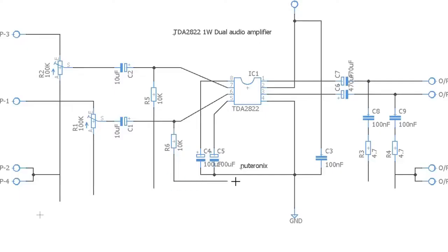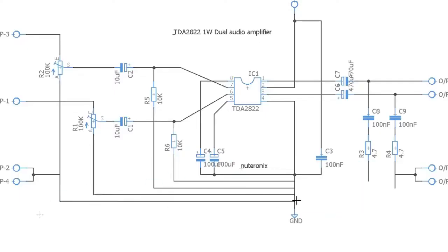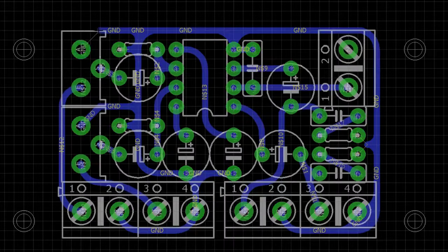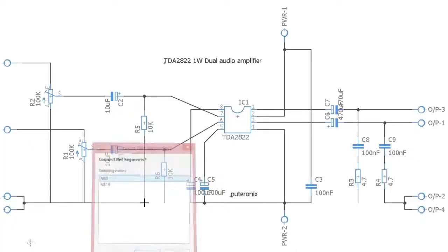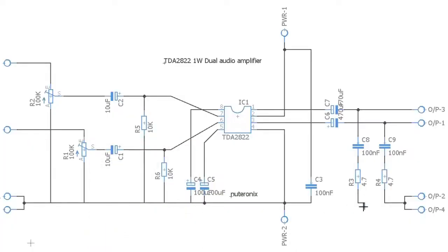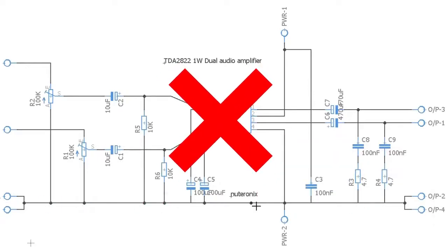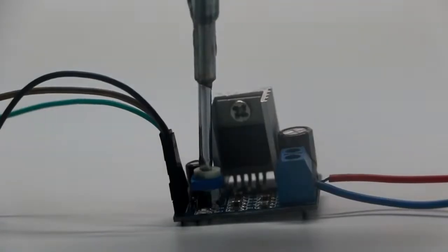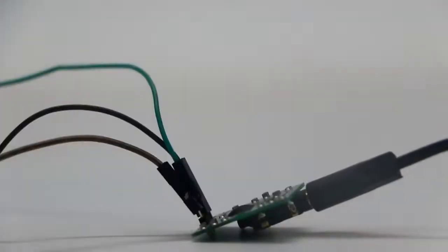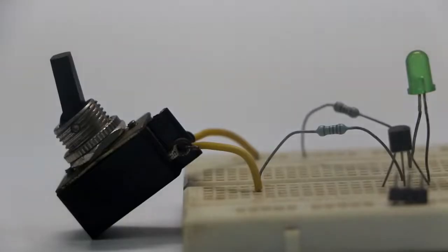When you design a PCB or wire a circuit, provide individual traces when connecting different signal references back to the ground or common node. Avoid interconnecting references together and then connecting them to the common node. Doing so will result in a humming sound or noise in analog amplifiers. This also applies to wiring of input or output jacks, tone and volume controls, and switches.